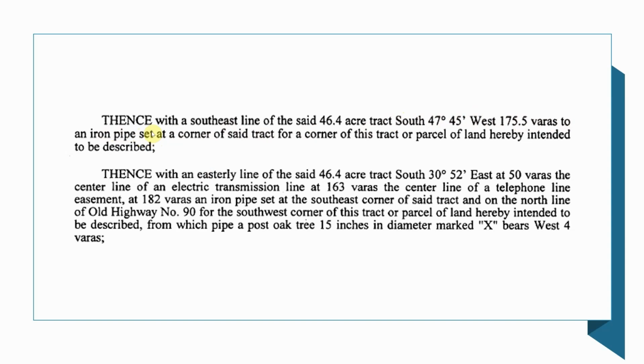This is where your field work ties into your legal description, why you need to make sure that you understand the difference between some of these words. So this is a legal document, and that's kind of why it's written the way it is. It's very explicit. It means what it says. So whenever you write legal descriptions in the future, like for your final project, think about that. Think about set and found. Those are very important things to remember.